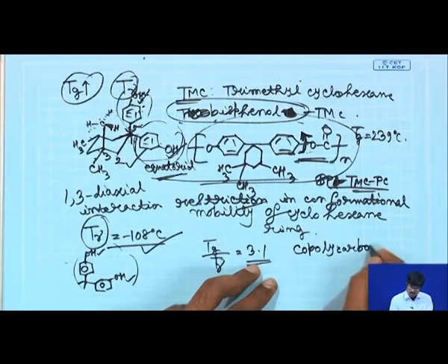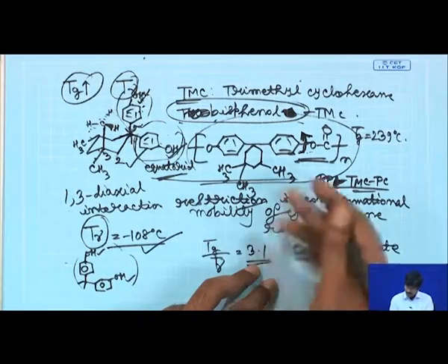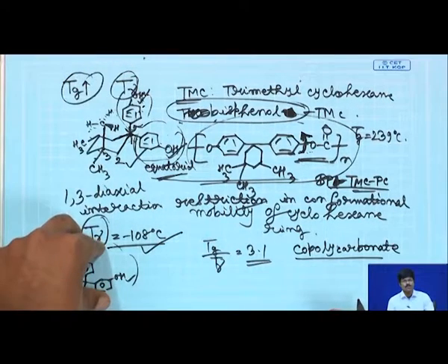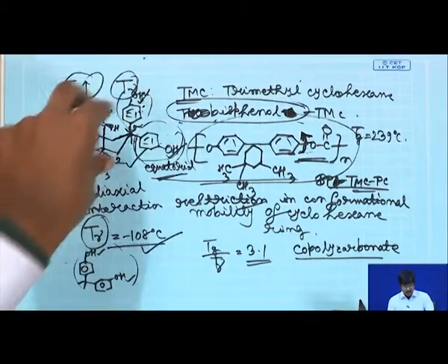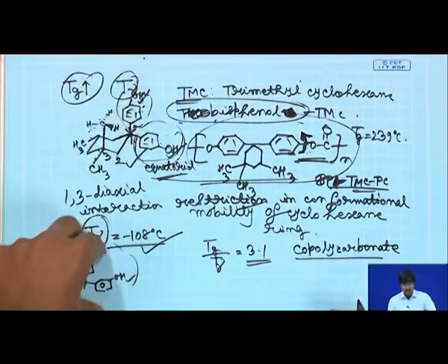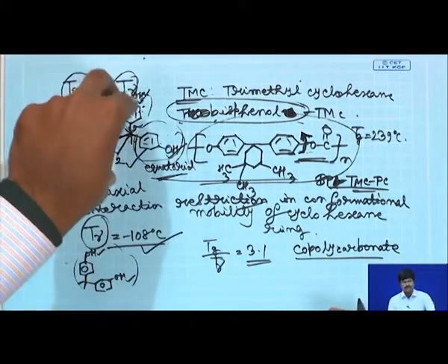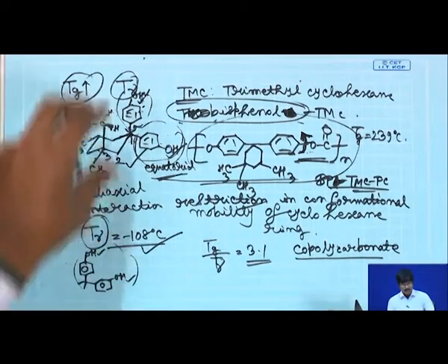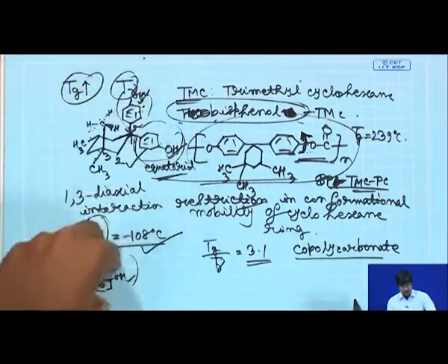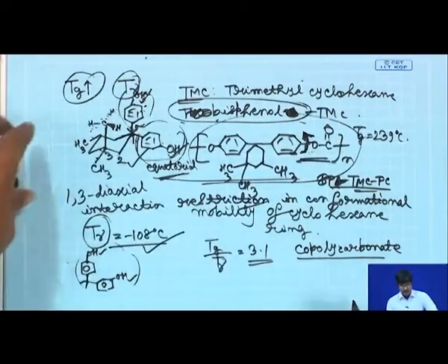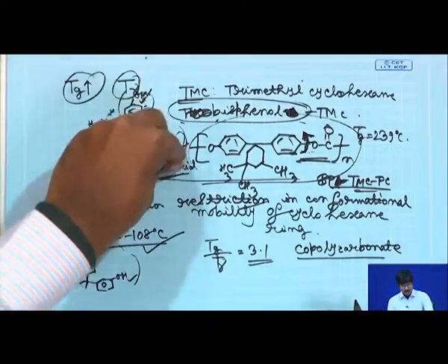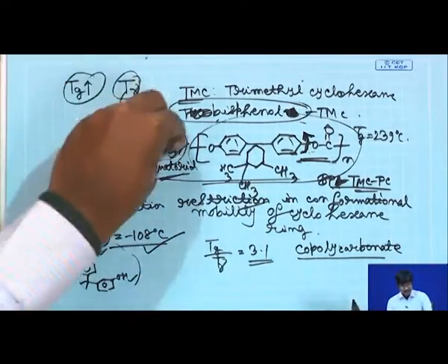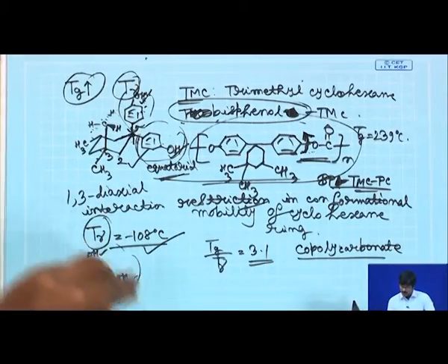You mix them together during the copolymer preparation, and then you will have both this monomer as well as this monomer present in the polymer, and you can change the relative ratio of them depending on how you start. Depending on the relative ratio of the monomers in the starting copolymerization mixture, you can introduce these two components in different ratios in this polymer backbone, simply because these phenolic OH groups have very similar reactivity to the phenolic OH groups in this bisphenol A.